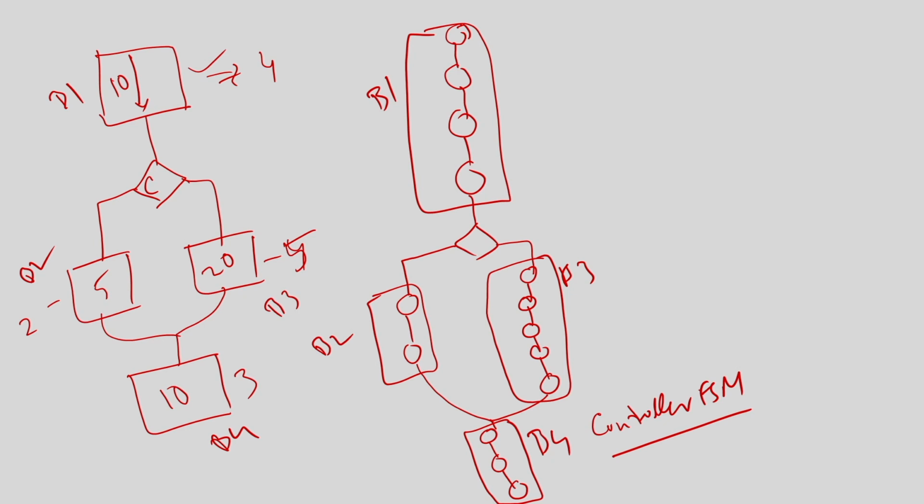Now, try to understand one of the drawbacks here. I have come up with a very efficient, very optimal algorithm, but it is only applicable to one basic block. You cannot merge this scheduling with that, because they are taken independently. Two basic block schedules cannot be combined, because I have not taken them together. As a result, the final latency of the design is not optimized across basic blocks. It is optimized within a basic block, not across basic blocks.